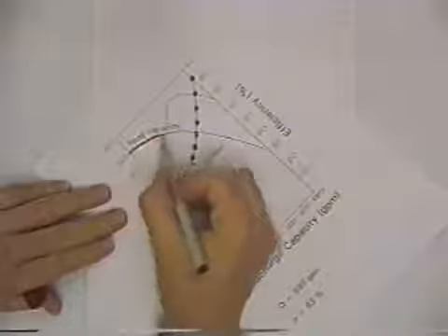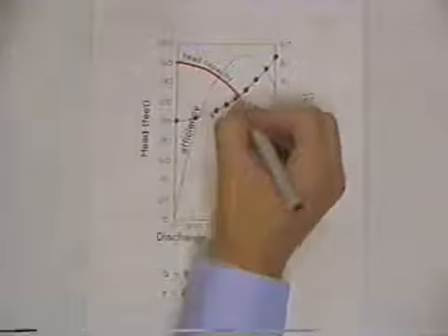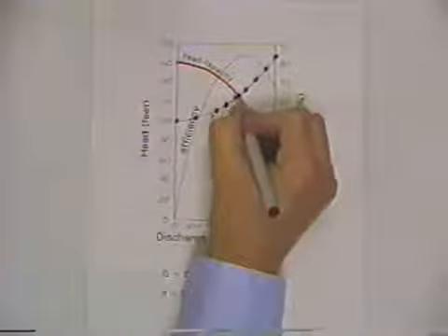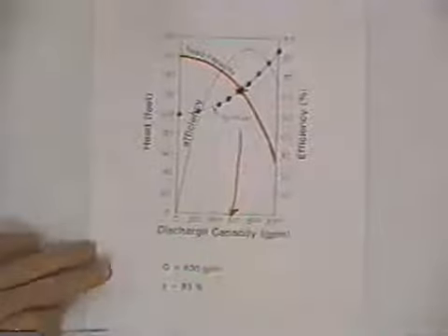And then the pump itself is characterized, and this would not be computed, this would have to be given. It's determined in a laboratory. And so what would the discharge be? Well, both of those are good relationships, and this is the point in which they're both valid. And so that point would set the discharge rate.